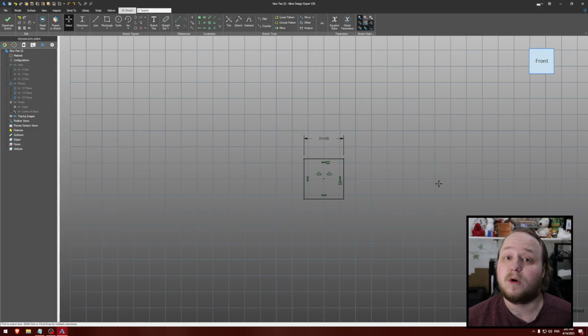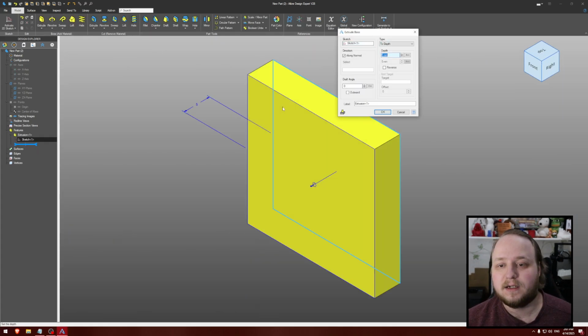From here, we're going to extrude. So, your CAD software should have some kind of button that says extrude. Now actually right here, Alibre doesn't look like it does, because it wants you to deactivate the sketch first, but you can actually skip that step in Alibre if you have a keyboard shortcut for extrude, and I do. I set mine to E. Whatever your keyboard shortcut is for extrude, go ahead and find it, or just click the button on your toolbar.